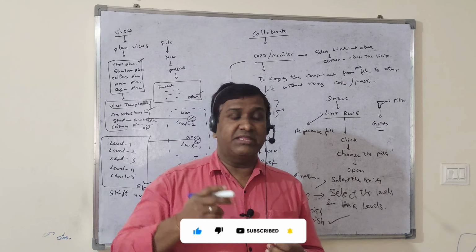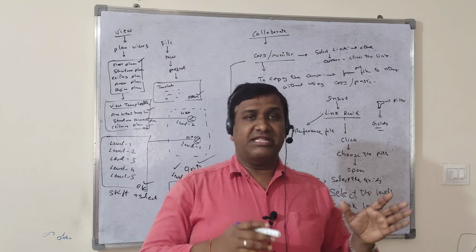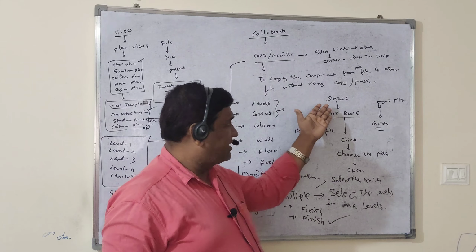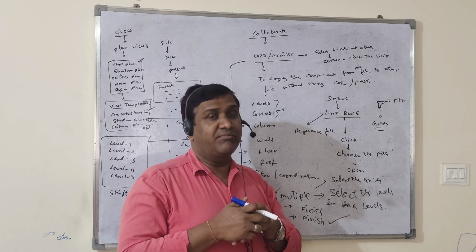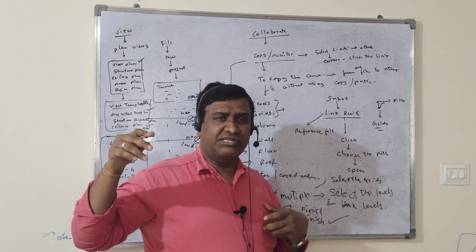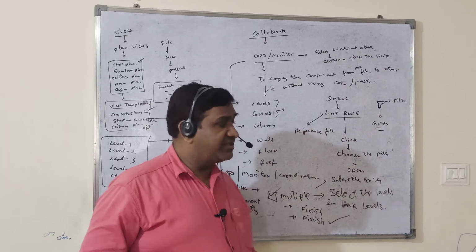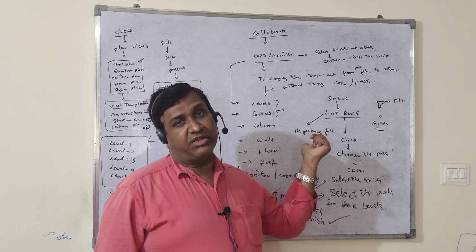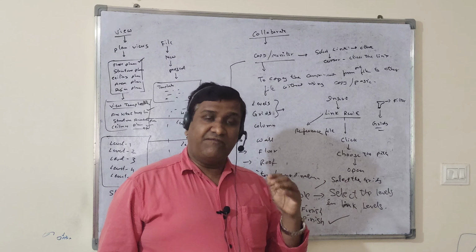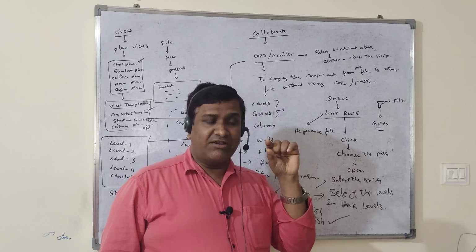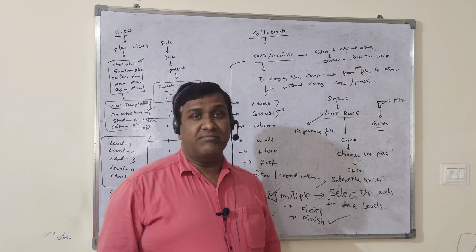But if the architecture team has given the model, at that time they have to link the file once again and match the levels and grids again. Maybe in the architecture team some of the levels may vary, some of the grids may vary, so if such changes happen, you also have to coordinate with them. But it's a risky situation, because if one grid or one level value has changed, the entire project is going to be disturbed. So at that time it is very risky.